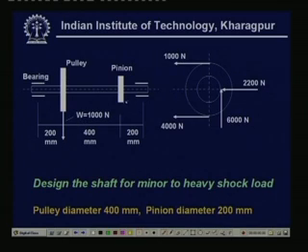The pinion should have some weight but it is not specified, and the dimensions of the shaft etc. are given here. This pulley is acted upon by belts whose tensions are 1000 Newton and 4000 Newton respectively. But for an actual design, one has to find out from the idea of belt drives what the tensions actually acting onto the pulley should be.